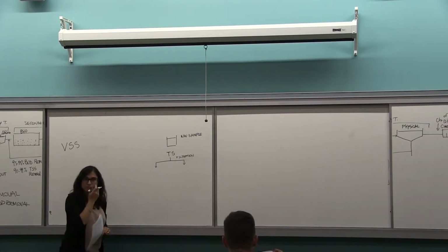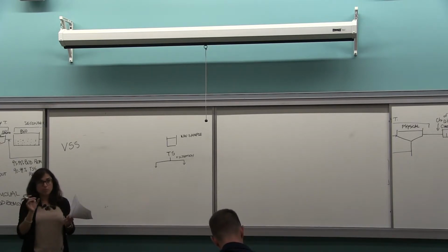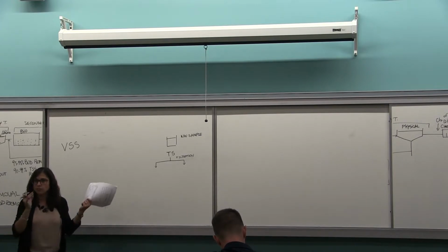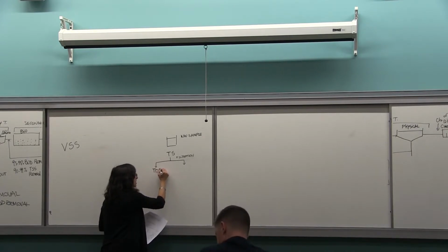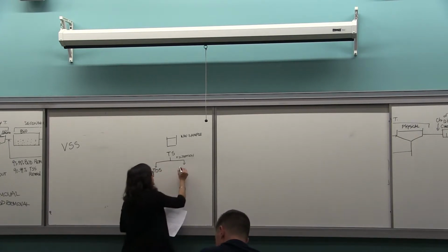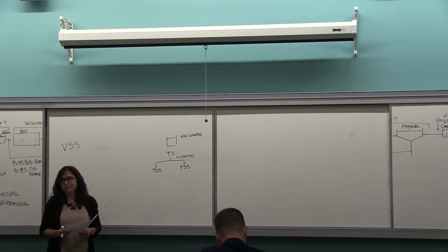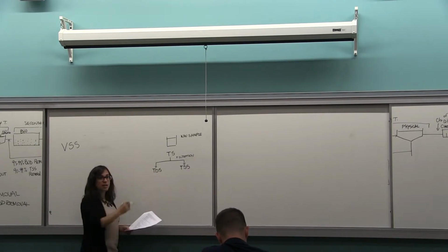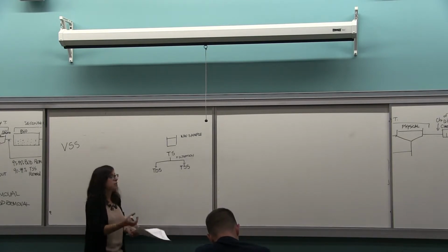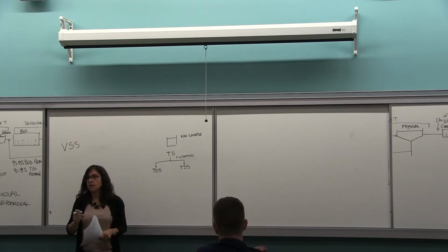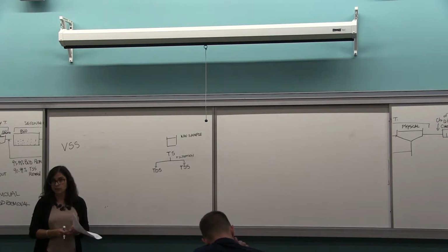If I filter those solids, and the pore size is a specific standard, usually 1 micron opening, I'm going to have the total dissolved solids and the total suspended solids. The total dissolved solids are so small that they pass through my filter and are present in the water. The total suspended solids are large enough to be taken away, so that we can collect them in the filter.